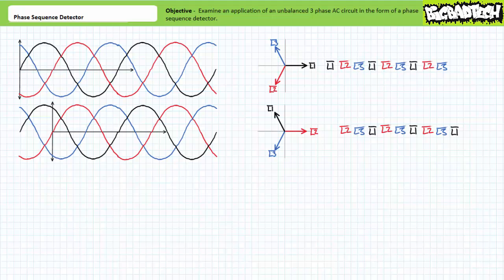As previously, using the plot of voltage as a function of time or the phasor representation, the sequence of these three waveforms can be determined. Given L2 is established as our frame of reference, we can state L2 peaks, then L3, then L1. When extended for another cycle, the sequence again repeats itself, L2, L3, L1. Given the repetitive nature of these waveforms, it should be noted that the choice of reference has not changed the phase sequence, only the starting point within the same sequence.